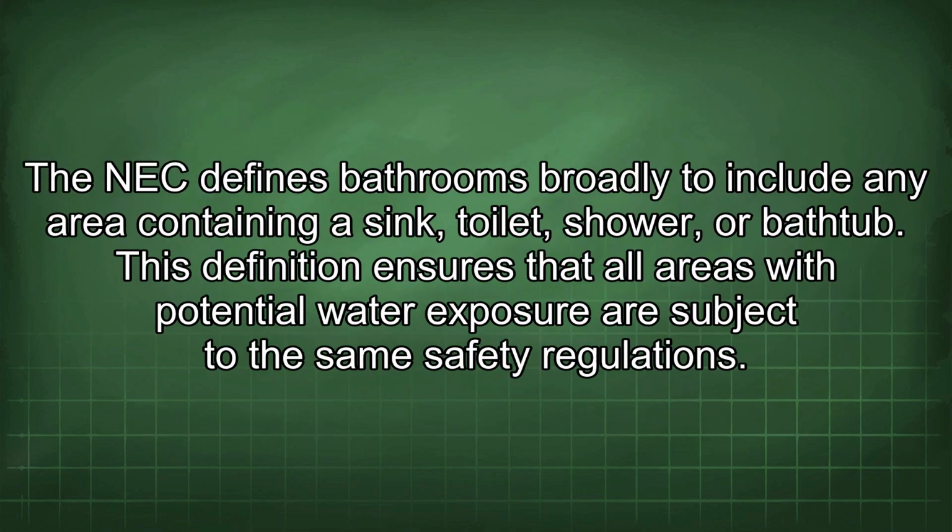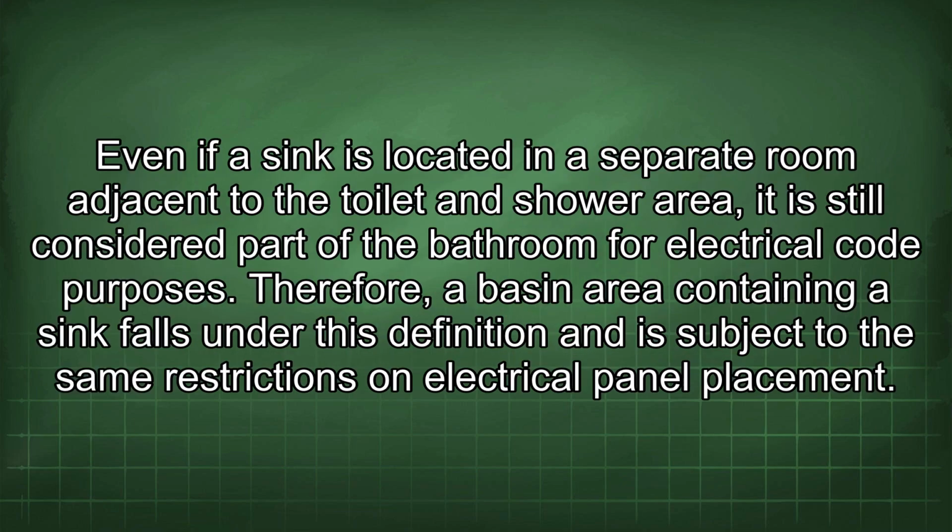The NEC defines bathrooms broadly to include any area containing a sink, toilet, shower, or bathtub. This definition ensures that all areas with potential water exposure are subject to the same safety regulations. Even if a sink is located in a separate room adjacent to the toilet and shower area, it is still considered part of the bathroom for electrical code purposes. Therefore, a basin area containing a sink falls under this definition and is subject to the same restrictions on electrical